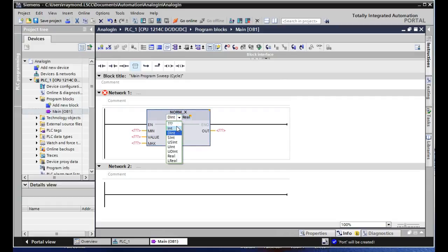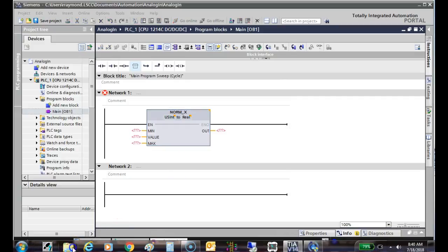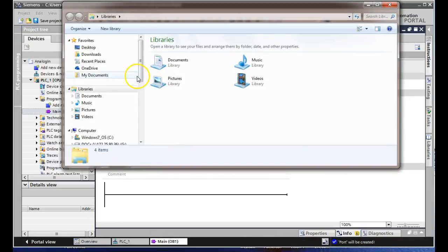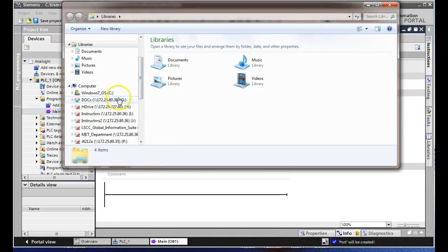Well, literally we can come up here and change that. So literally over here, I think this is 16 bits. We need to make sure it's got to be 16 bits. I could come up here and use that because what I'm getting off my AD converter is always positive, right? You understand that? It never goes negative. That makes sense? USINT.